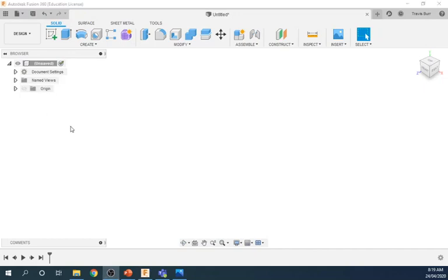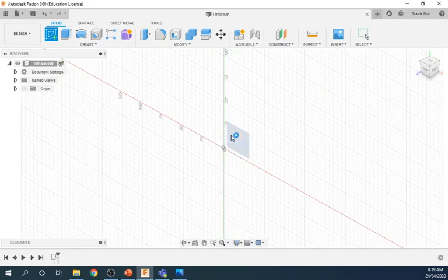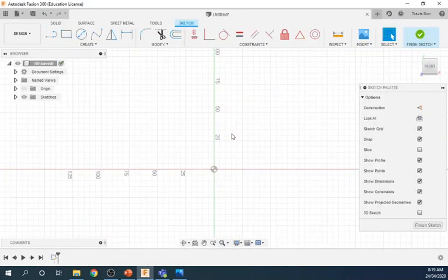So once in the workspace, I am going to start some new sketches. I'm going to go Sketch, pick a work plane, and start off by drawing the side of my piece. So for the side, we had our depth. I've got my line started.